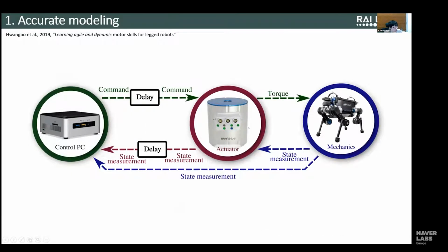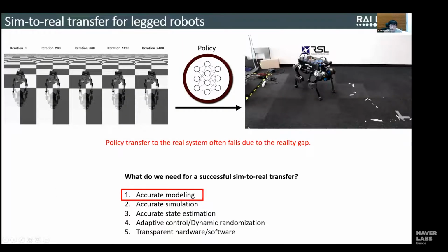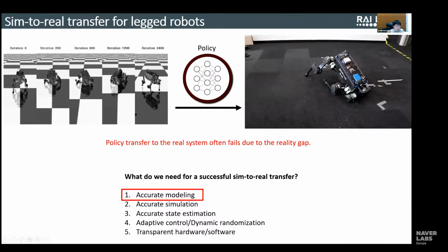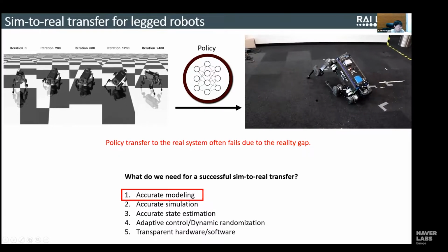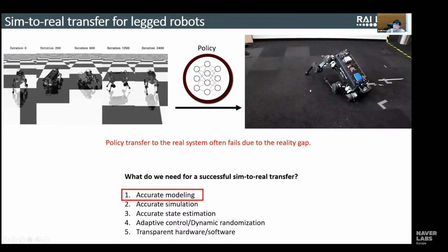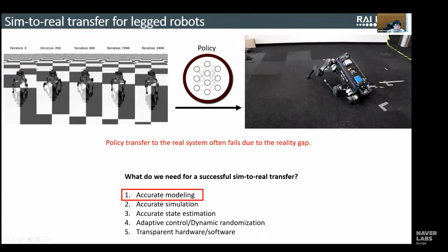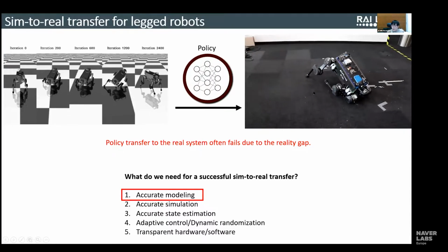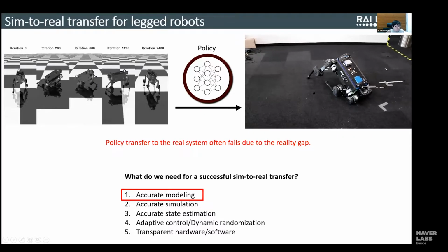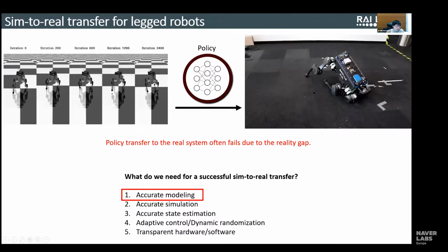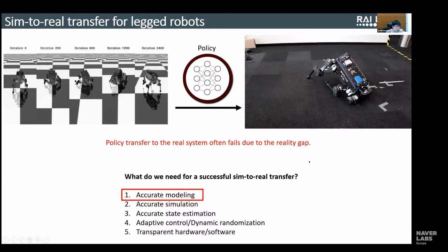And if I show you what happened when I tried to implement this on the real system, this is how it works. We train the control policy in simulation, we deploy it directly on the system, and it failed like this. On the right is the same system. We've been working hard to do system identification. For each link, we measure the weight. The inertia is hard to measure, but we estimate it as best as we can. The lengths are given by the CAD model, so they are pretty accurate. That's what we did, but it still failed.